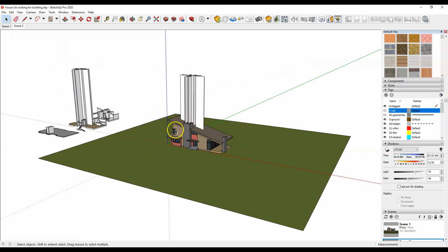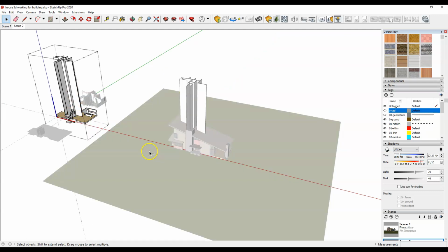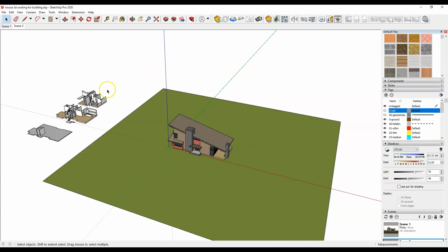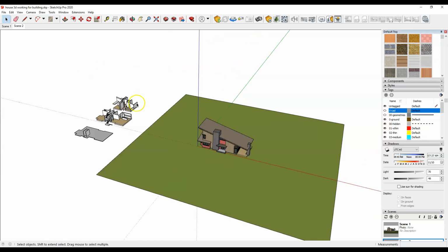So that's another pro tip, if you will, for 3D modeling: model your interior off to the side, make a component, or wherever the software allows you to edit it, copy it in, so I can do all my edits over here, knowing that they also change on the interior of the building. Of course, I'm going to undo that. That just looks super silly. So that's how you would do the interior stuff.